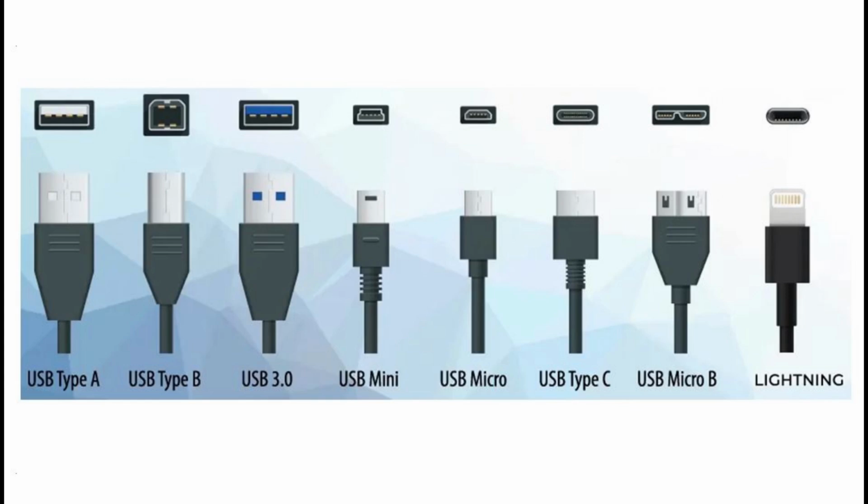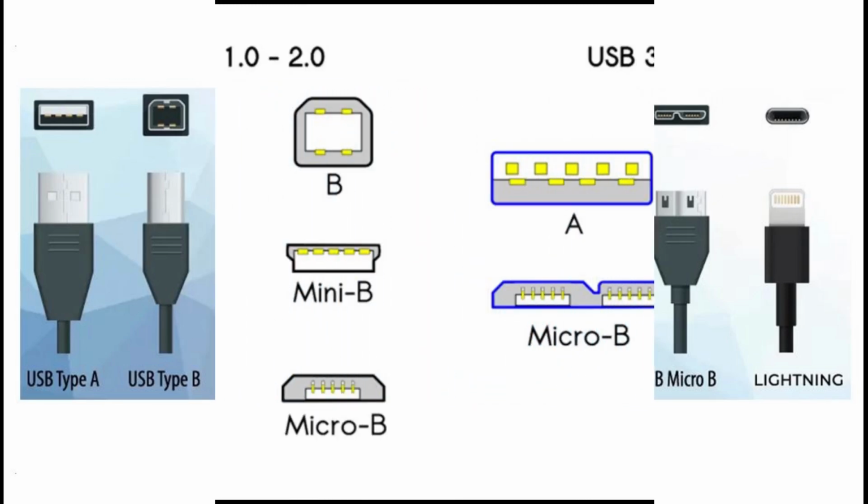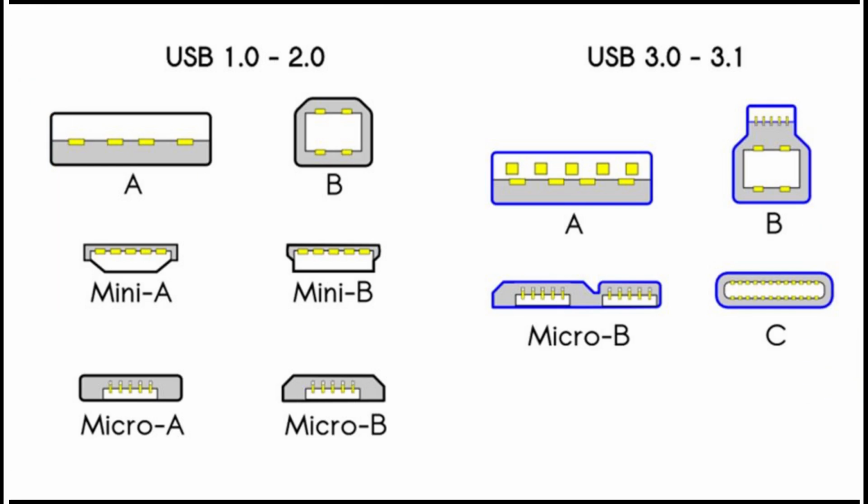USB 4 enhances the data transfer and power delivery functionality with a connection-oriented, tunneling architecture designed to combine multiple protocols onto a single physical interface so that the total speed and performance of the USB 4 fabric can be dynamically shared. USB 4 particularly supports the tunneling of the Thunderbolt 3 protocols, namely PCI Express, PCIe, Load/Store Interface, and DisplayPort, Display Interface. USB 4 also adds host-to-host interfaces.